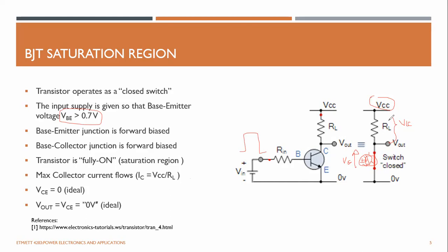As a power electronic designer, you always like to have the total power supply voltage appearing across your load, with nothing going across the transistor. That is a waste of power. So when selecting the lowest voltage drop transistors, you can run your system more efficiently.